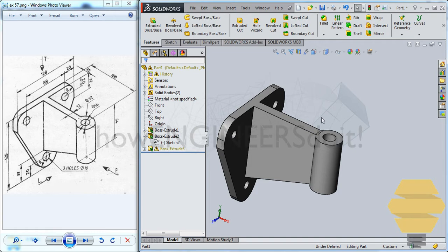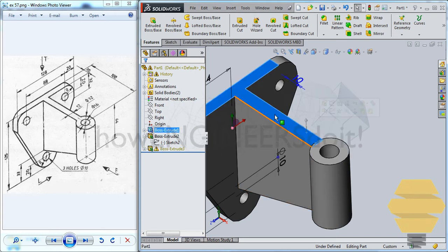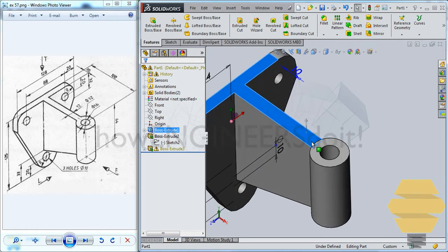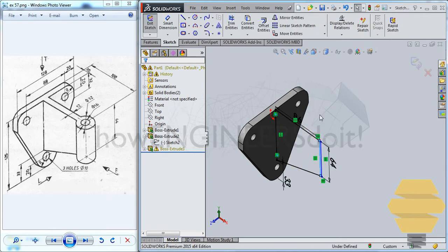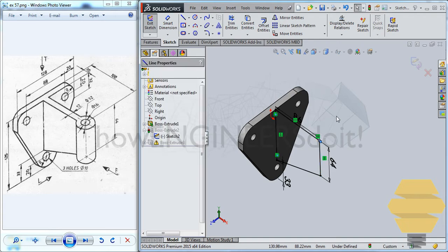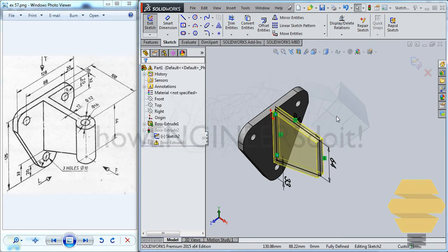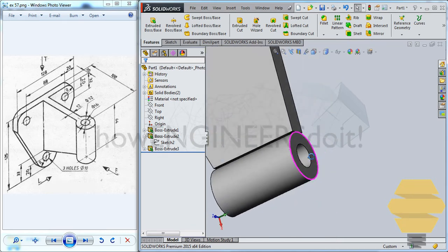The reason SolidWorks threw an error is because this particular feature was constructed based on this surface. So when this surface is getting modified, it'll definitely throw an error. So for you to solve such a problem, what you can do, okay, so now we've completely come out of it.